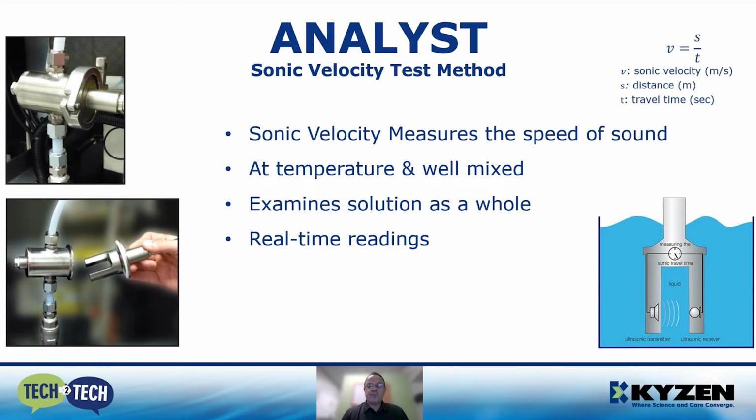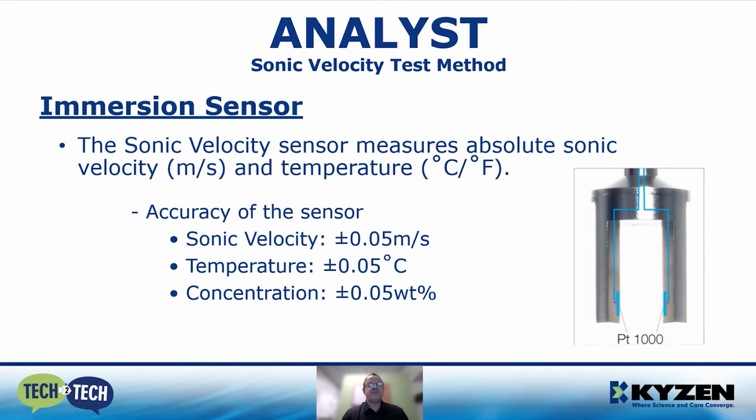There are also real-time readings. You don't have to wait. There is no waiting time. Automatically, you are getting real-time readings. It's also a very accurate sensor. It works in immersion, and the sonic velocity measures absolute sonic velocity in meters per second and temperature in degrees Celsius or Fahrenheit, whatever you choose. The accuracy is very, very good and consistent across the board.